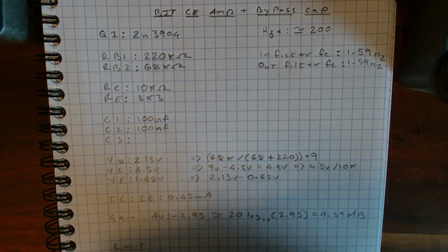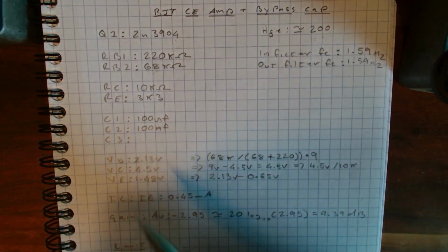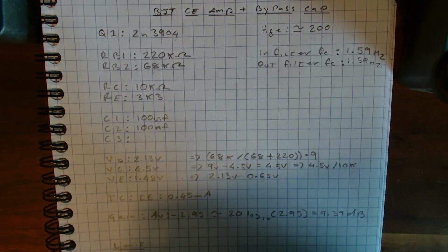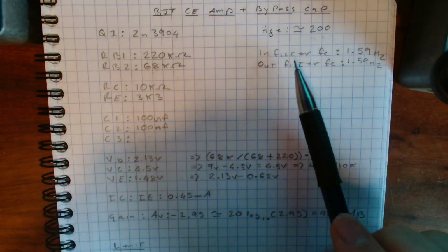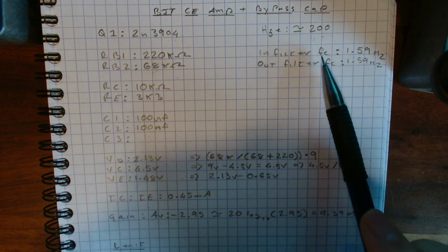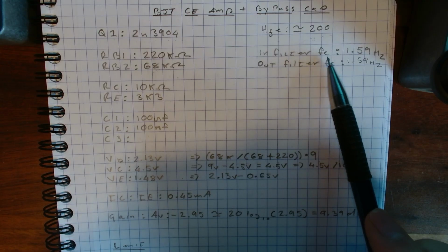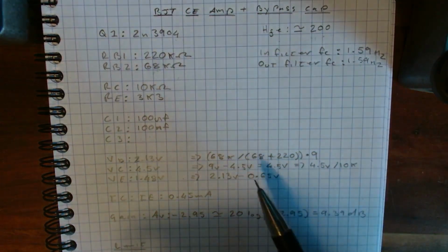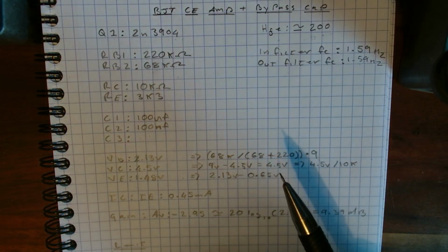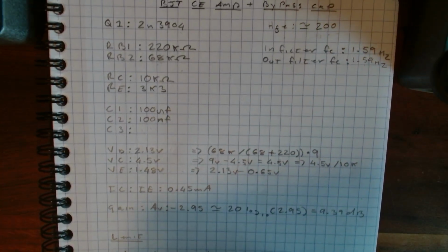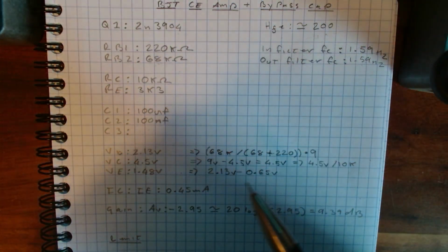This C3 we're going to come back to in a later video. This is a little trick you can do to get a little bit more out of the circuit, but I'll cover how this works when we've got more circuit to play with. And again here, this is just the check sheet so that I didn't forget our input and output filter cutoffs. So the cutoff frequency where it's going to filter from, that's in the 1.5 to 1.6 range there. Now, you can't see it on the schematic, and we're going to go through the actual circuit in a minute and we'll be able to measure these things.